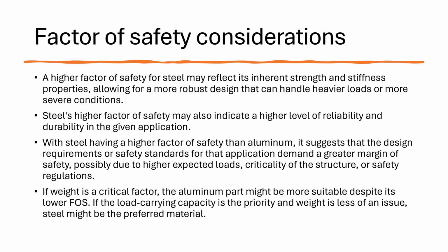With steel having a higher factor of safety than aluminum, it suggests that the design requirements or safety standards for the application demand a greater margin of safety, possibly due to higher expected load, criticality of the structure, or safety regulation. If weight is a critical factor, then aluminum might be more suitable despite its lower factor of safety. If the load carrying capacity is the priority, and weight is less of an issue, then steel might be the preferred material.